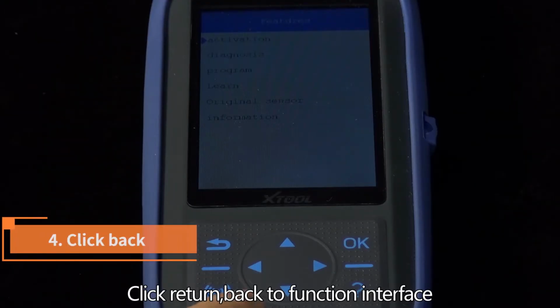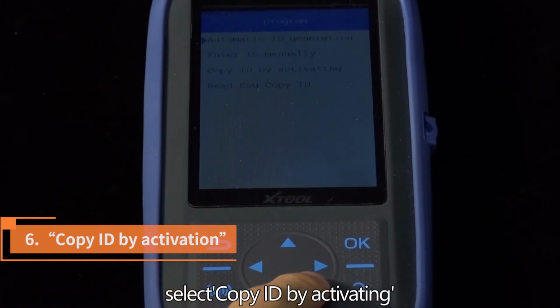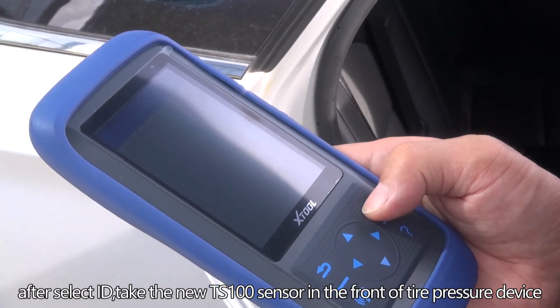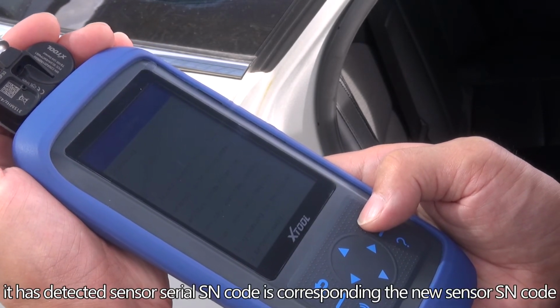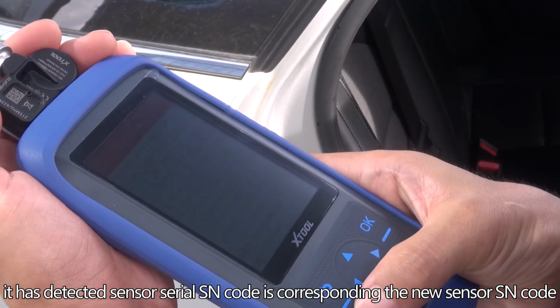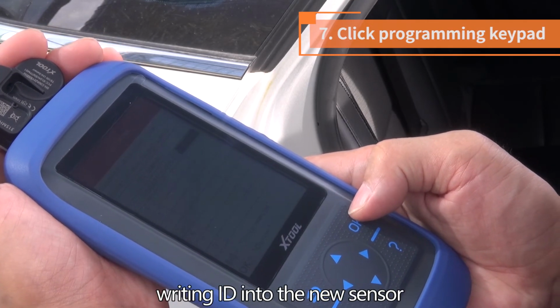Click Return to go back to the function interface, select Programming, and select Copy ID by activating. After selecting the ID, take the new TS100 sensor in front of the tire pressure device and enter the programming interface. It has detected that the sensor serial SN code corresponds to the new sensor SN code. Click the programming keypad to start writing the ID into the new sensor.